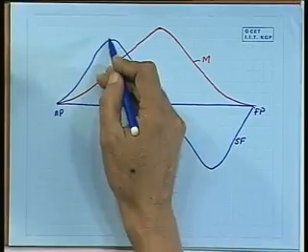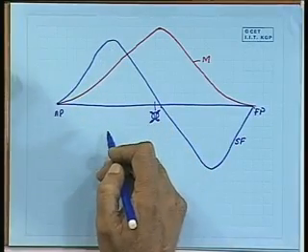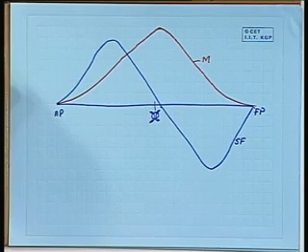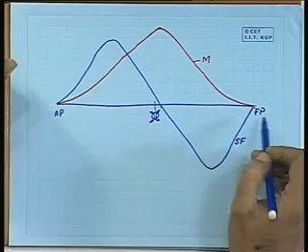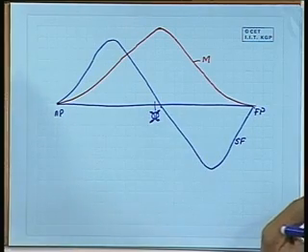And the maximum shear force which we can see, either positive or negative, is somewhere near L by 4 from the ends. Now, these conditions fulfill our basic boundary conditions, because when the ship is floating in water, the two ends are free, and therefore we say that a ship girder is floating in water in free condition. Ends are free. How it flexes is a different thing.